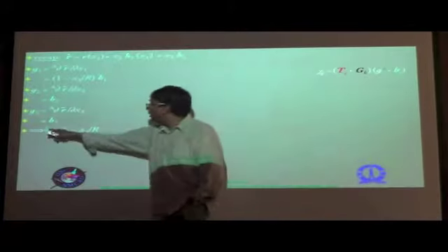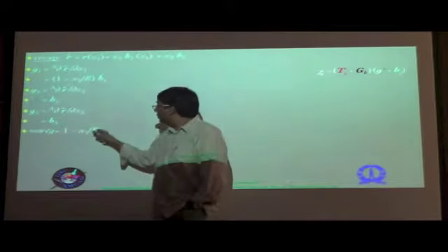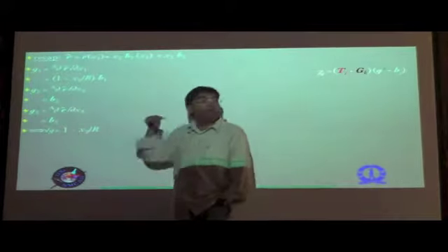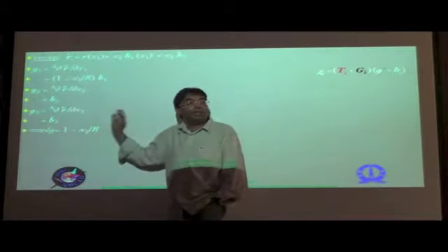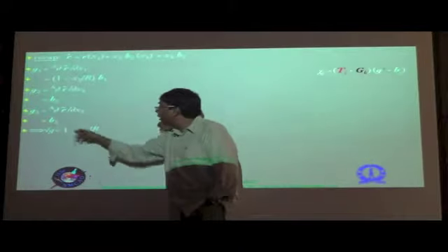Your G2 is much more direct, because the only term in which x2 figures here is here, and the derivative with respect to x2 would just be b2 alone. Similarly, your G3 is just b3 coming from this term. Okay? And then from these three you can get the determinant of the metric tensor and then its square root, and that is nothing but 1 minus x2 divided by r. Okay, so if you had curvature in the other direction, x3 divided by r in the other direction with the appropriate sign would have contributed as well, but that is not to be. We are talking about initial curvature in only one direction, and therefore this is all that is root g.